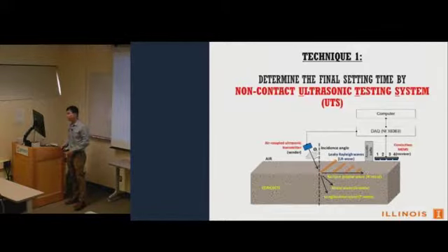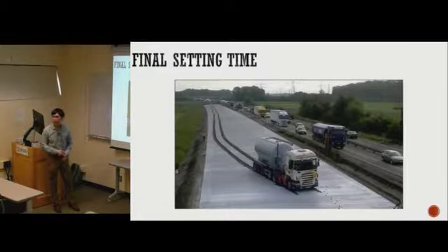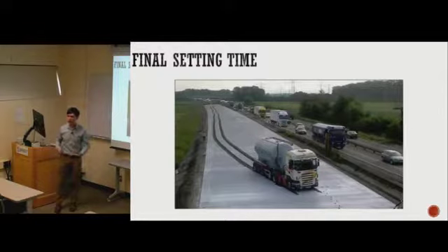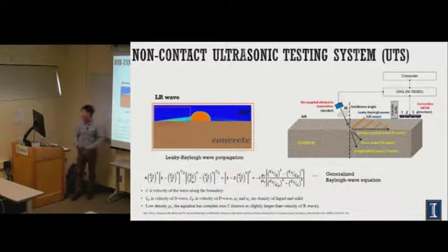So the first technique I want to introduce to you is the ultrasonic. So what do you see from these pictures? Looks like a big mistake, right? Someone doesn't know when the concrete sets, but is still rolling on it. So it's very important for me to know when the concrete sets. So that's why we use the ultrasonic and utilize the wave called the leaky Rayleigh wave.